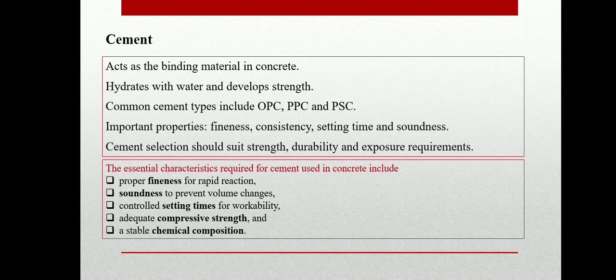The bottom line here is cement selection isn't arbitrary. It has to suit the required strength, durability, and the specific exposure conditions the structure will face, whether that's a marine environment, a sulfate-rich soil, or ordinary atmospheric conditions.